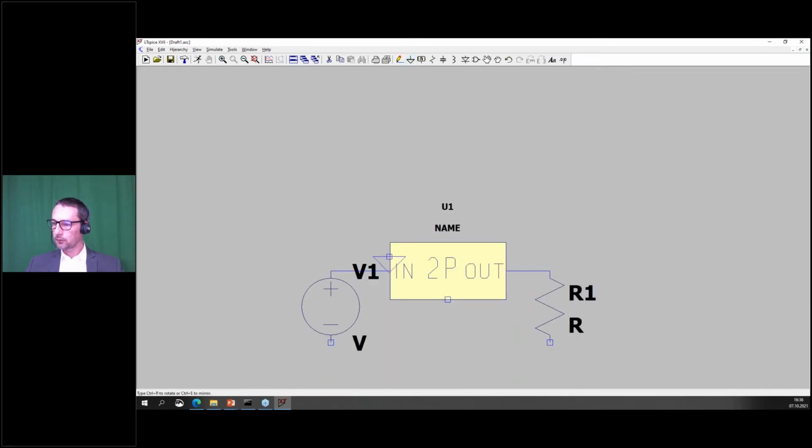And I forgot, we need some ground connections, otherwise, without a ground connection, we will not have any signal result. Then we set the termination resistance to 50 ohm, and we also give the source the 50 ohm. We are in a 50 ohm system. That's pretty nice. So we are prepared now.